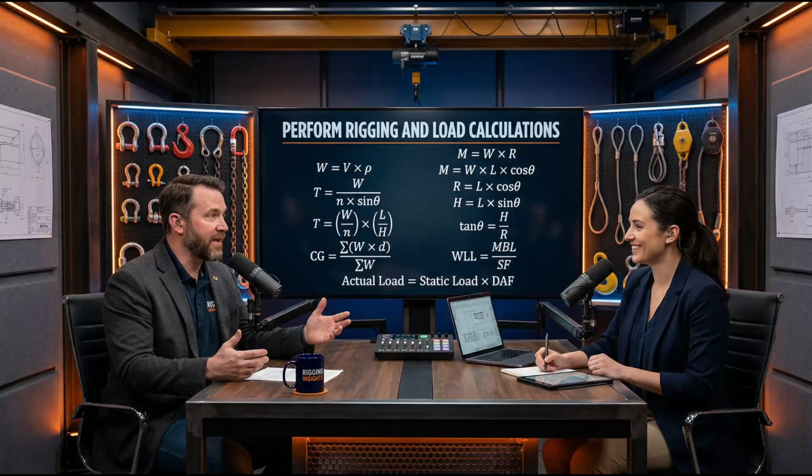This massively increases the overturning moment, the leverage the load has to pull the crane forward. This exact chain of physical events is how massive multi-million-dollar cranes get tipped completely over into the dirt by a rogue gust of wind. It explains why international regulatory frameworks are so intensely strict about weather conditions. The sources highlight port regulations in Egypt, which mandate a hard stop, a total cessation of all lifting operations if the wind speed exceeds just 20 kilometers per hour.